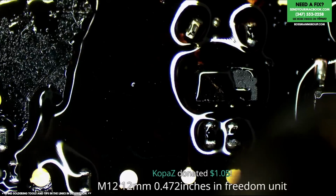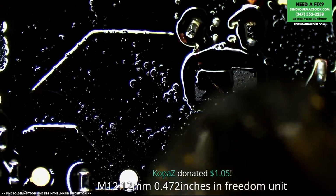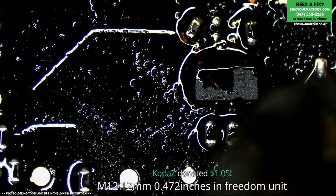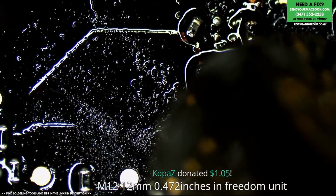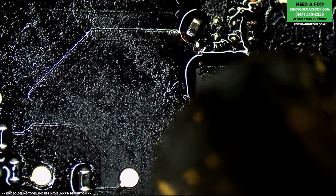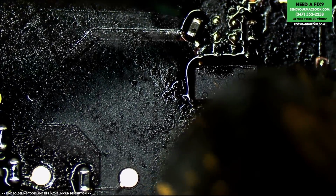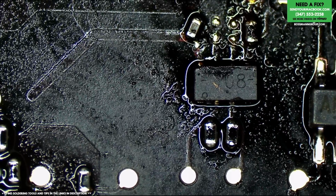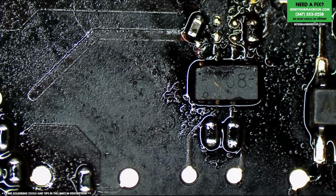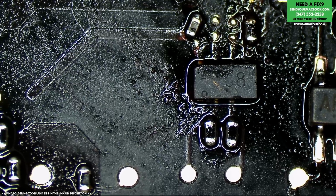Hot air it into place nicely, so I want my jumper to be where it's comfortable. Not just where I put it, I want it to actually flow to where it would be comfortable, because that's where it's going to be most stable long term. Now, I want this to be able to survive getting dropped, all sorts of things. I want this to survive all the abuse that I should expect a Mac owner to inflict on their product.